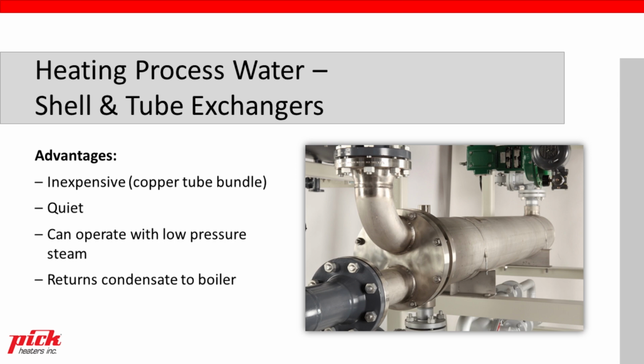Next, let's talk about shell and tube heat exchangers, the indirect method. The advantages are that they're typically inexpensive, especially with a copper tube bundle. They're quiet. There's typically no sound generated from indirect shell and tube heat exchangers, and they can operate on low pressure steam.